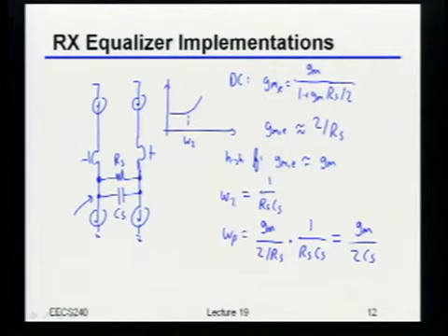So just in case it wasn't clear, where'd that magic factor of 2 come from? Our buddy whose effect we quote all the time: the Miller effect, right? Because we tied those caps up across the two differential sides. Okay? This sort of makes sense to everybody?